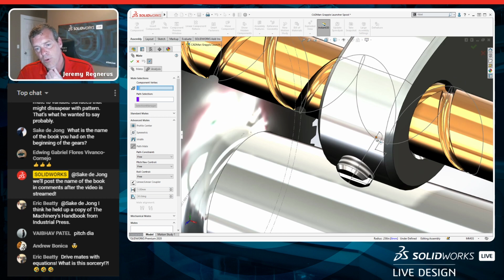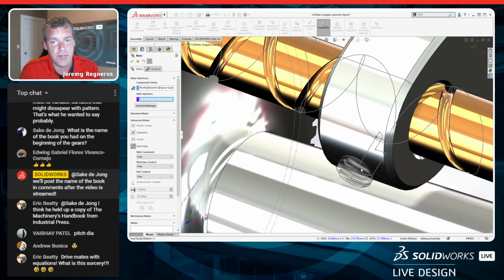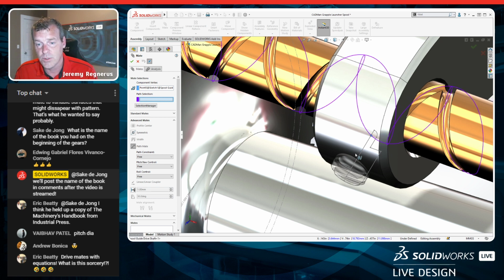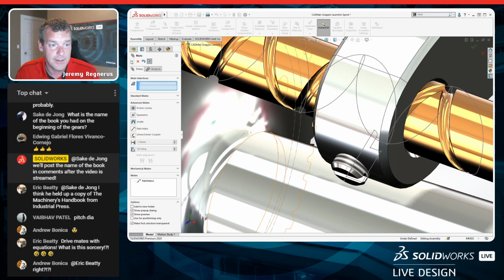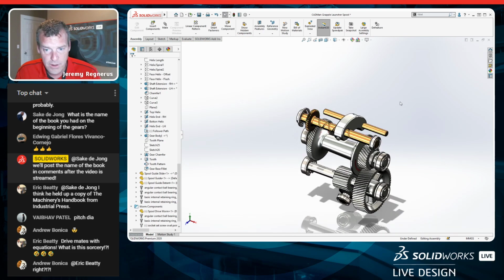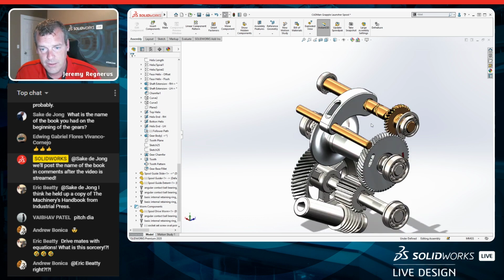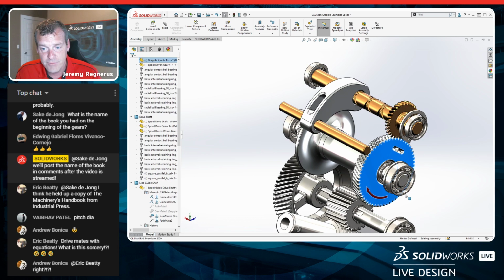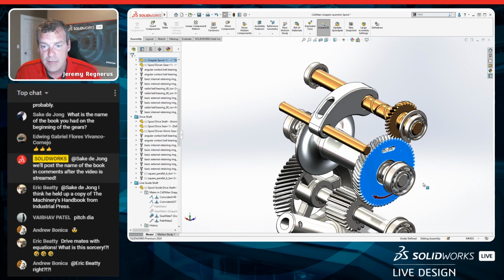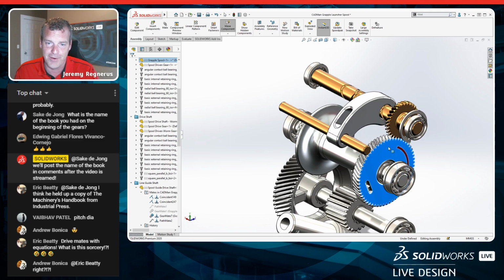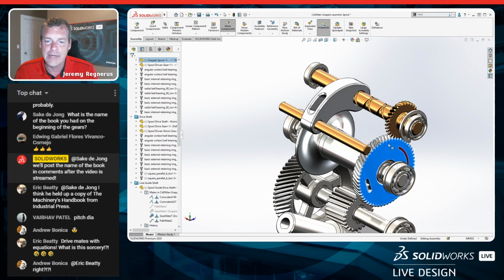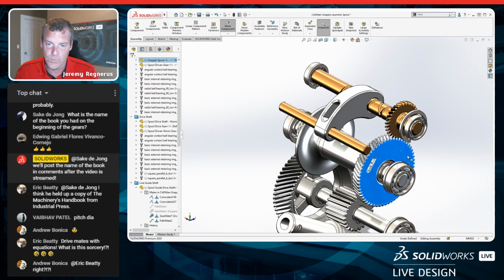We can tell a point, any point, this could be a vertex of a model edge, a sketch entity, whatever you want it to be, to follow along a sketch. And I'm going to follow along that path, and hit OK. And now if I turn all these sketches off, you will see that everything works together. Because that sketch wraps back around on itself, that's a 3D sketch, a very complicated sketch, it allows that follower to come along with it.